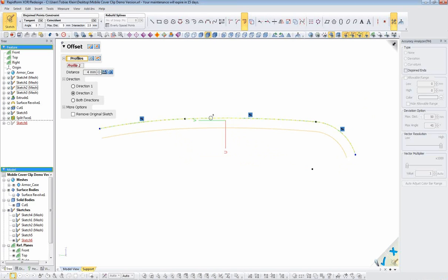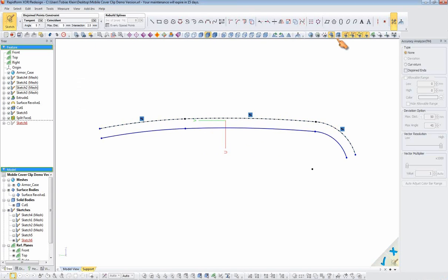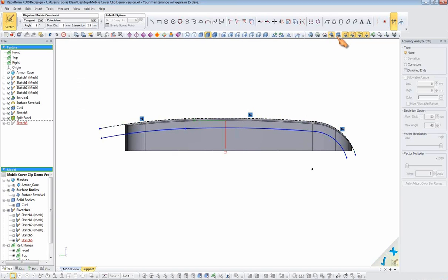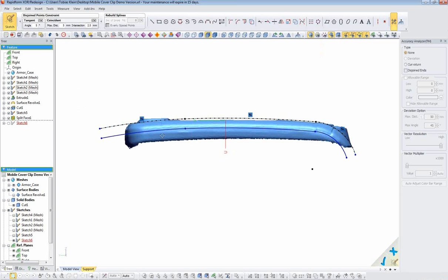and I can create an offset of that line, and by just looking at that model we can see there is some light reflex here. In this case there is a fillet area, and on this fillet area the light has some highlight, and I move just the lines that highlight pretty accurately actually.